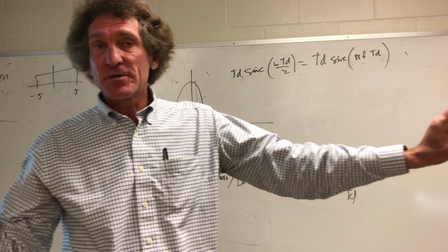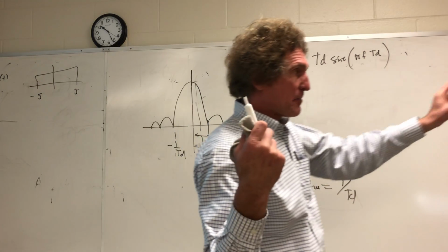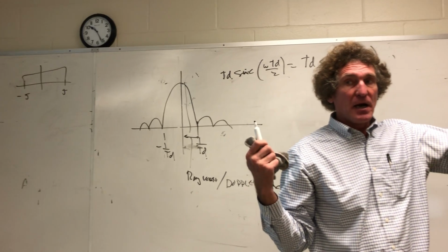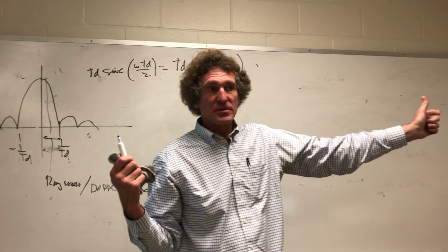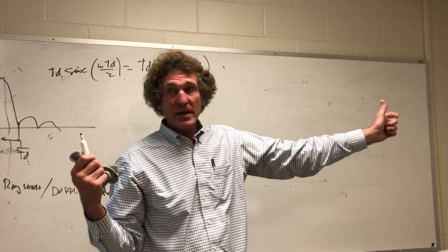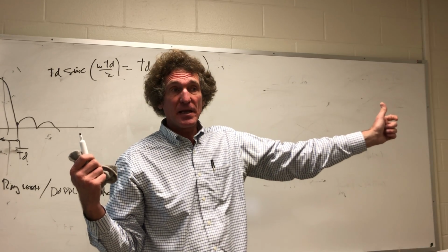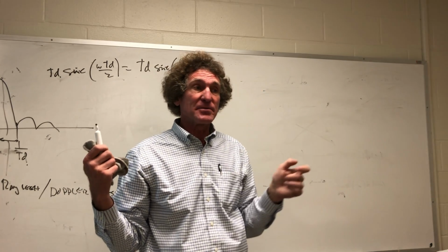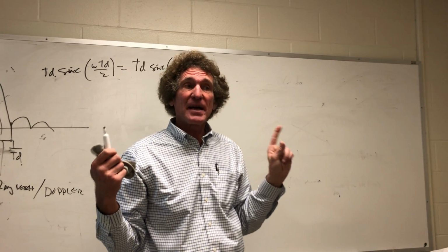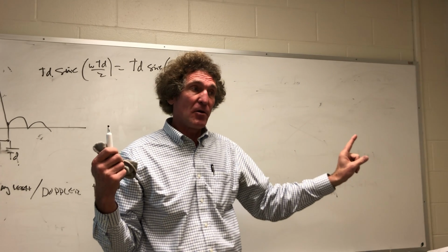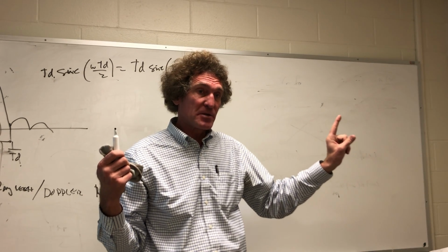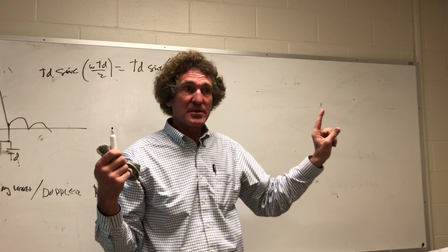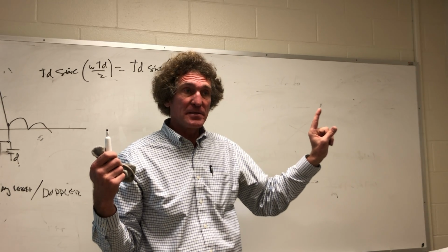Now that begs the question of, well then, how long does a cop have to actually have you in that radar beam before he can collect the information? I don't know the answer to that exactly. It has to do with the size of the vehicle. But he doesn't get it instantly. Now, he does get it almost instantaneously if he has a laser. But with this, he has to have at least 1.5 seconds of dwell on your car to get a legitimate speed. All right? And that's because his range resolution needs that much collected information. Do y'all follow me on that class?